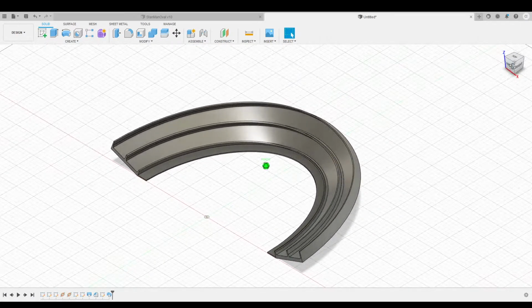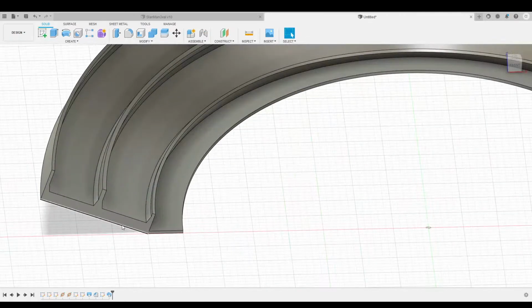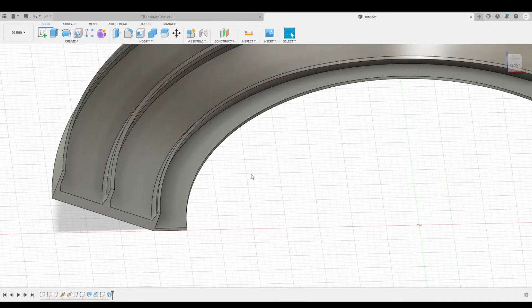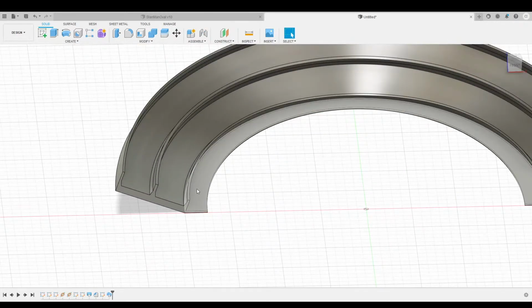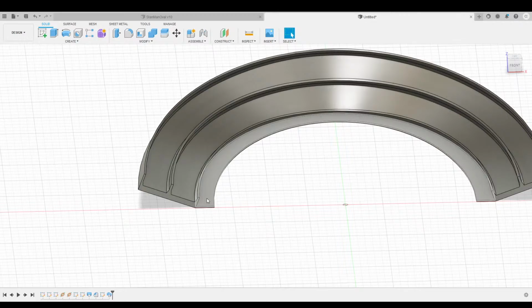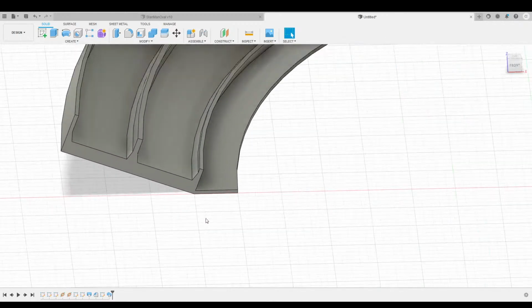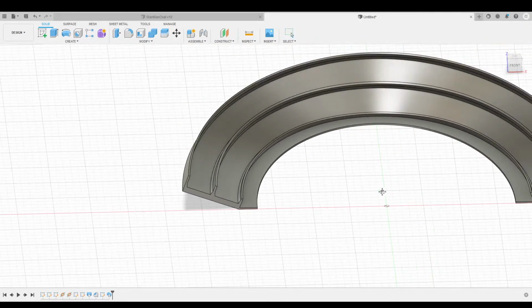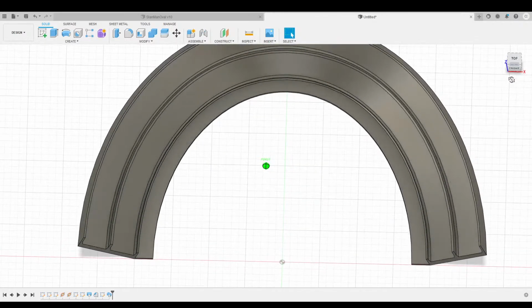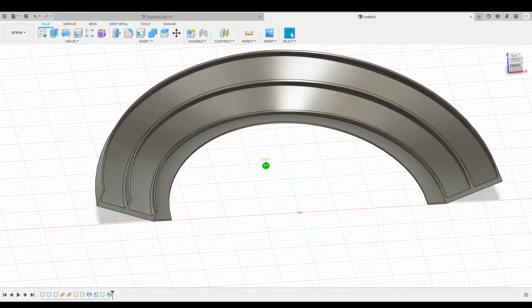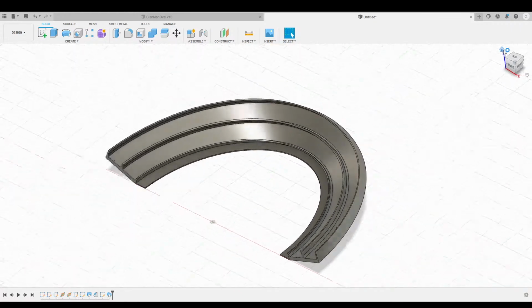So that's another simplification. We used to actually draw this part in the first sketch, and so that's just another thing that Fusion would have to try to calculate to Loft, and a lot of times it wouldn't actually make this totally flat on the bottom or the top, which is, you know, it just had these micro imperfections. When you tried to put it on your print bed, if you were printing it in this orientation, it literally would not be flat on the bottom, and it didn't make any sense why until I realized you could just sketch it and then revolve it, or you sweep it around there, and now it's actually like this. Okay, so we have our basic shape kind of in place.